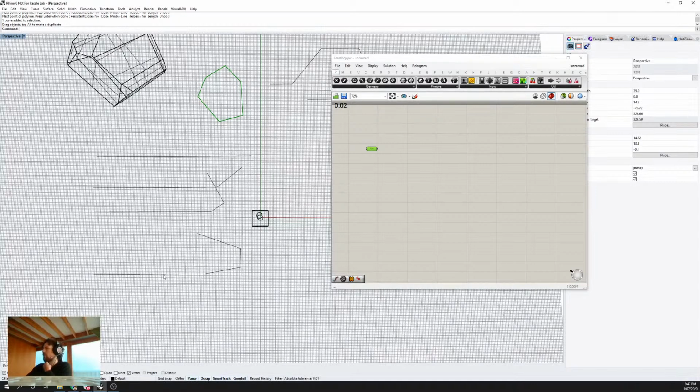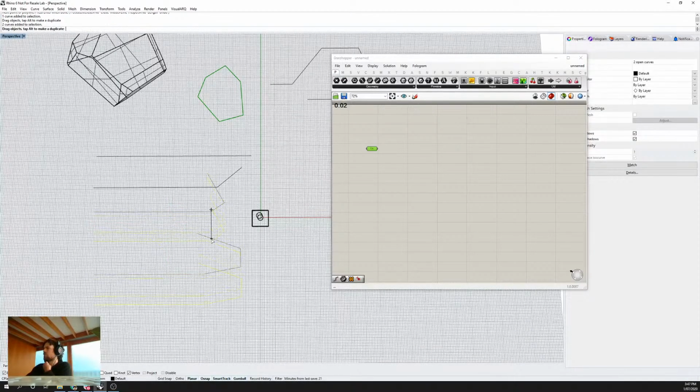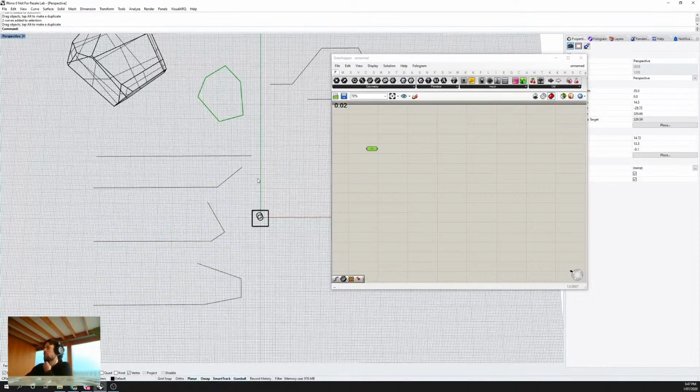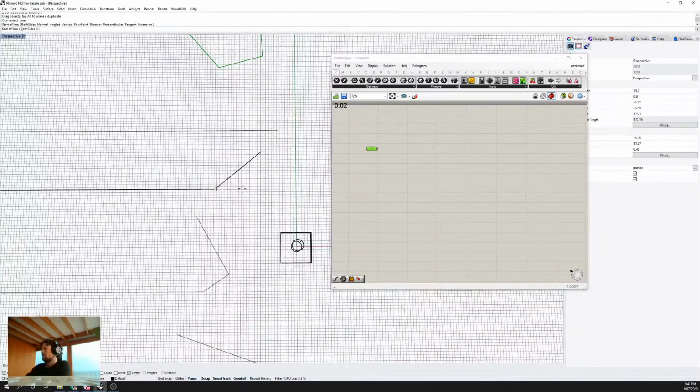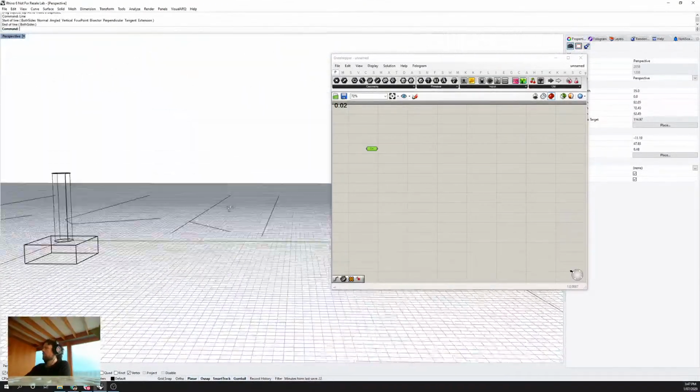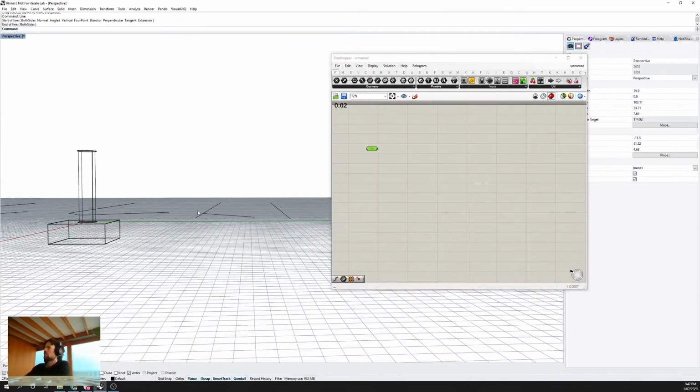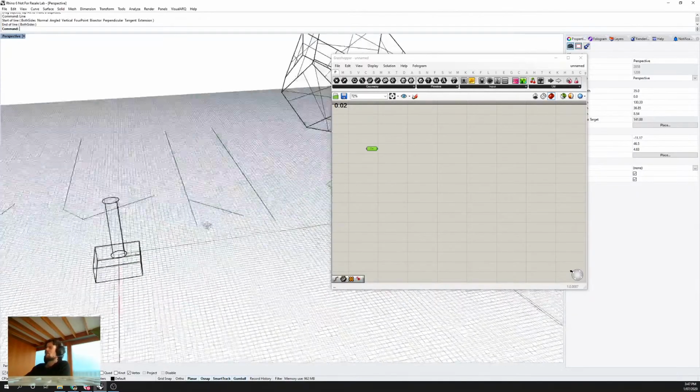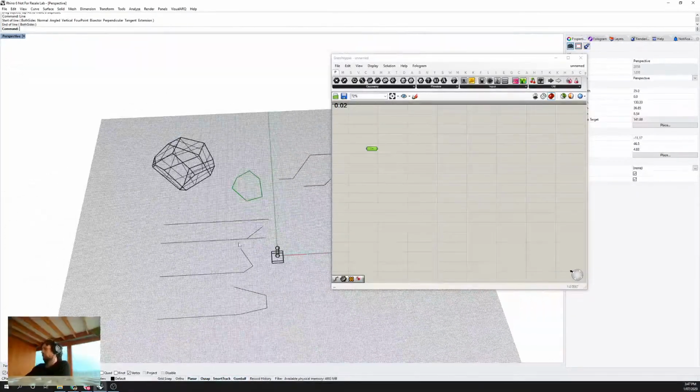So we're going to be gradually forming this shape, and we'll always have a straight section of remaining material. What our bending application really needs to show us is three things. We need to know how long this bent segment is. We need to know what the bend angle is. And we need to know if there's any 3D rotation of the part, whether we're bending it flat or in some other plane. Okay.